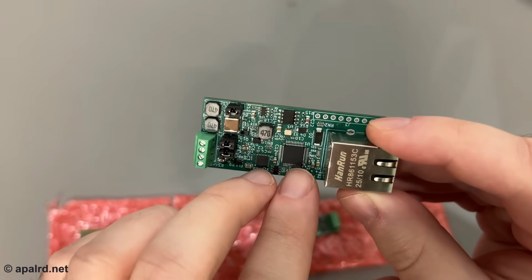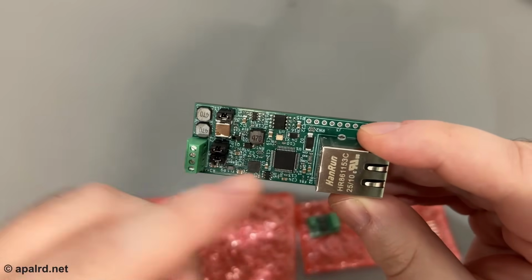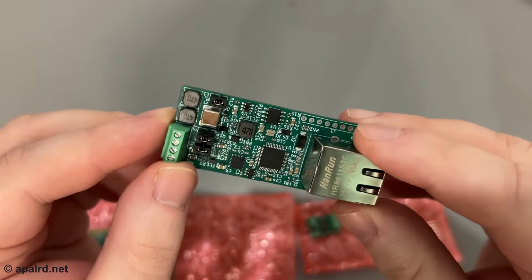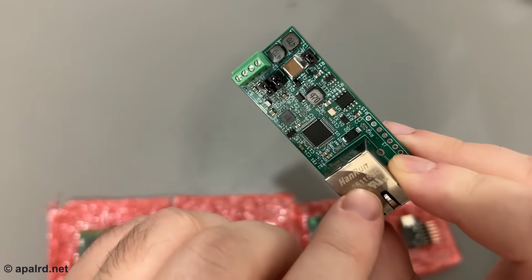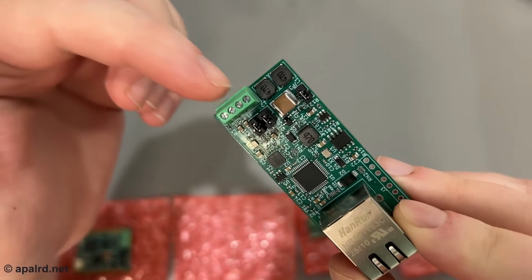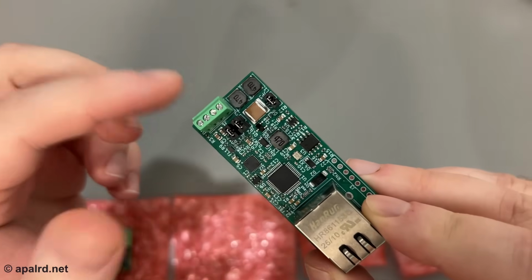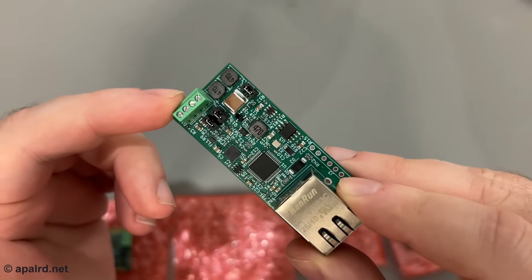But this is just a 2-port switch, so it's not doing anything to the Ethernet frames other than storing and forwarding them for one cycle, essentially. This also does PoE pass-through, so it takes in 48-volt PoE power here and sends that on to the 2-wire shared Ethernet bus, so you can power all the downstream devices, and that's how I've been powering everything today.